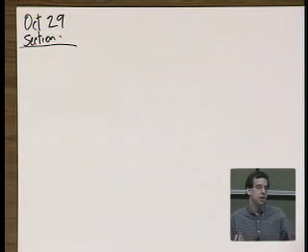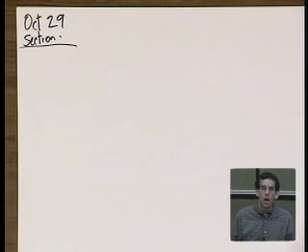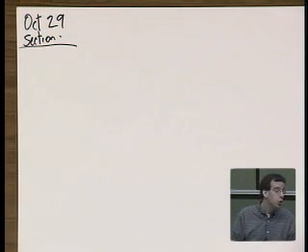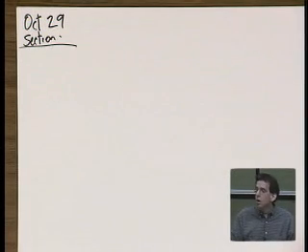So the design optimization is going to be a little different. You might use some of the other things you've learned to change your architecture a little bit. You could very well use an identical architecture to what you've used before. Chances are, if you did a good design for Project 1, it will be slow, because Project 1 didn't have any frequency response criterion. So if you did a 2-stage design, your first stage probably consumed very little current. So it has very low gm's and big r_out's and all that other stuff. So it wouldn't be able to drive the second stage with any decent frequency response. So you'll need to tweak some stuff.